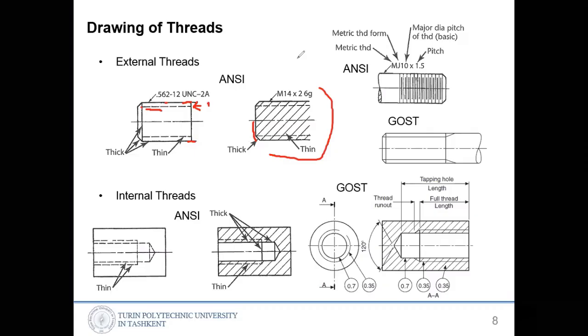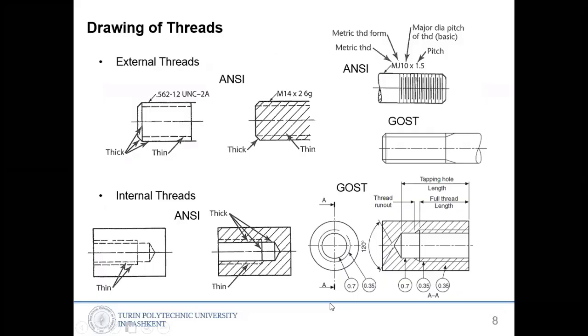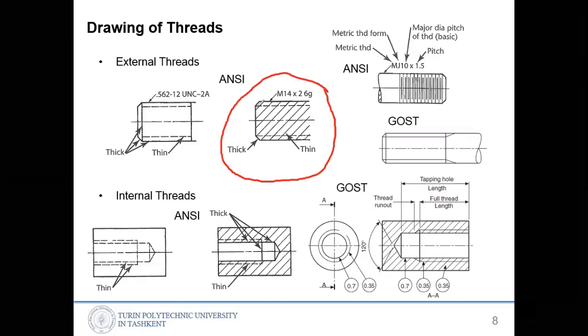But in our case, it looks like this. It's until the tip, so we have a thin line again. This one is a thin line. This is the section view, so we are continuing until we touch the contour, but this is the outside view, and it stops here at this line.